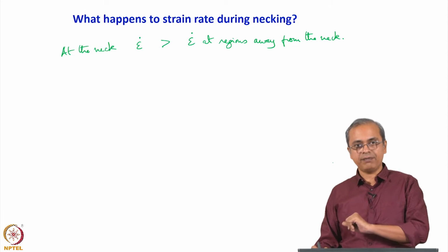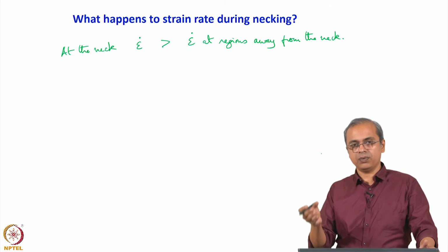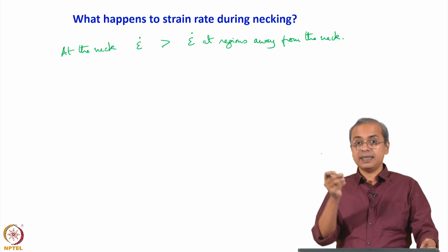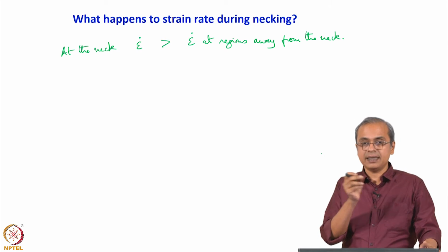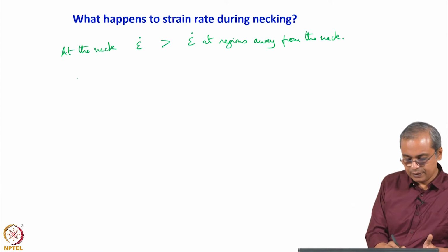at regions away from the neck, and that has simply to do with the fact that the region has become thin, stress is actually higher there, and the strain is no longer uniformly distributed.